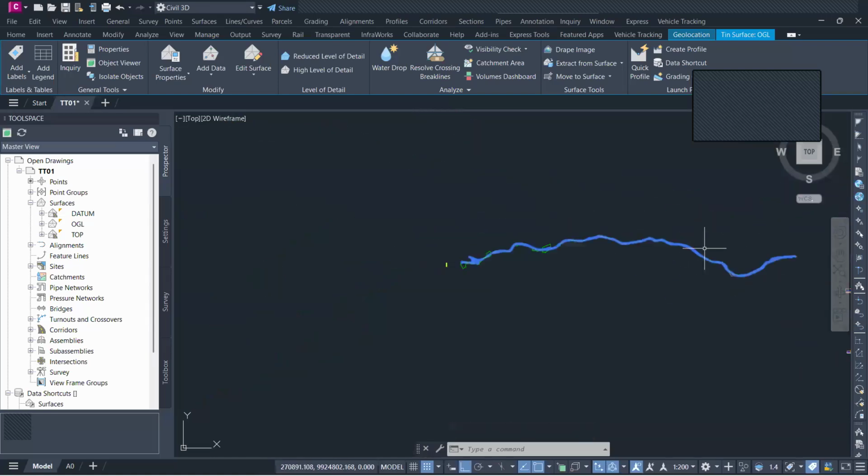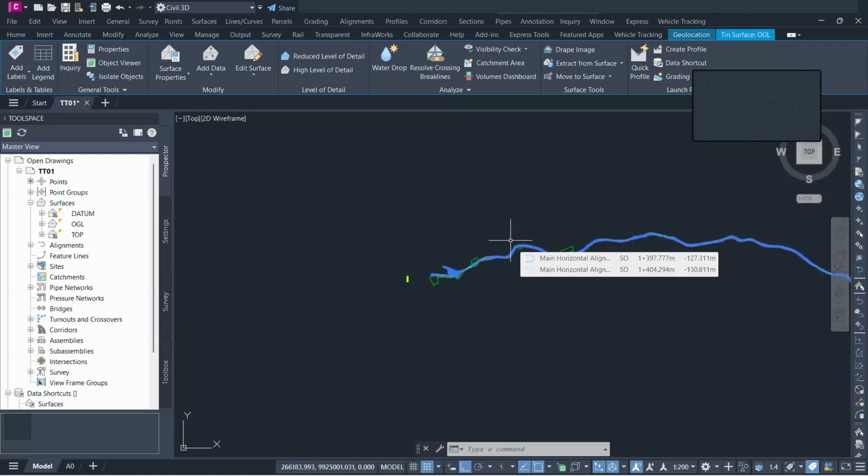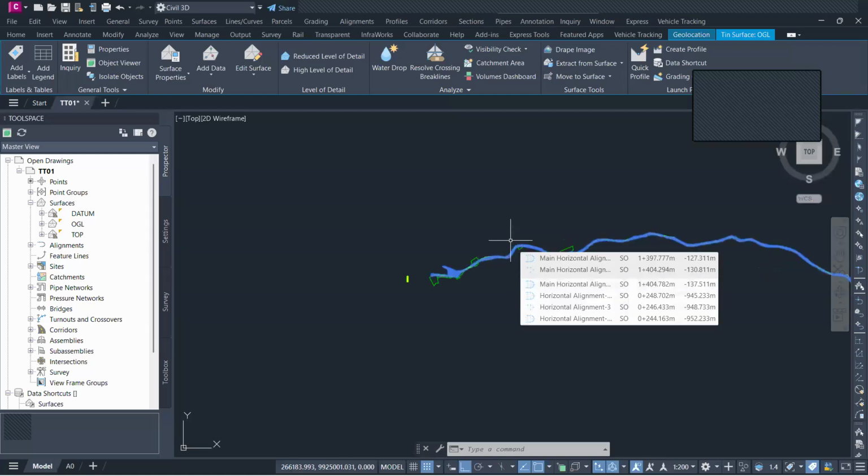So there are always two ways of calculating that. You may decide to use this method where there is the road corridor width, or right of way, of, let's say, 40 meters. And then topsoil stripping is, for example, 0.2 meters. That is 200 mm. So you're going to say 40 meters times 0.2 times the length of your section, so that you can get the volume, and the output will be in cubic meters. So at that point, you will have gotten the volume quantities for your topsoil stripping.